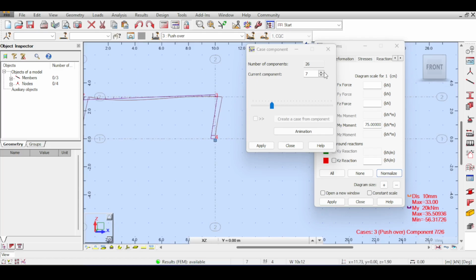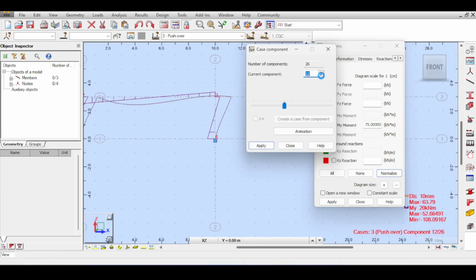And you can see that with each subsequent moment increase, you have two plastic hinges. You have 3 and 4, and you can see 4 has more moment. So I think 4 will fail first. You can actually see that suddenly moments in 4 don't grow. It somehow reaches a stable position, and then I think it should snap depending on the definition of our plastic hinge. Let's take a look. Yeah, it snapped.